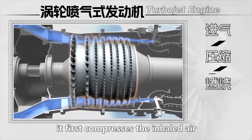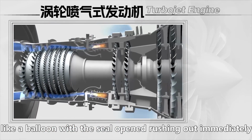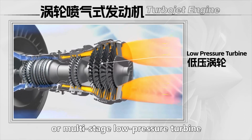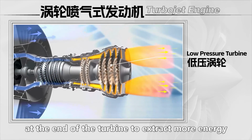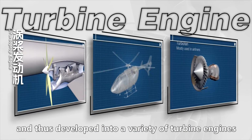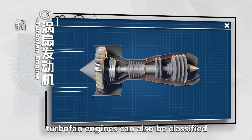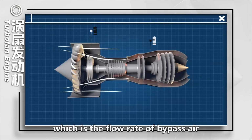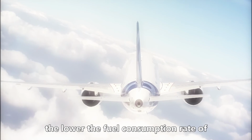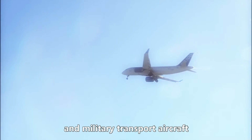It first compresses inhaled air, burns it, and then ejects it to provide power, like a balloon with its opening released and air rushing out immediately. Scientists added one-stage or multi-stage low-pressure turbines at the end of the turbine to extract more energy. This energy is used to drive different kinds of power sources, and thus developed into a variety of turbo engines. As an advanced version of the turbojet engine, turbofan engines can also be classified according to bypass ratio, which is the flow rate of bypass air to air passing through the core. A larger bypass ratio lowers the fuel consumption rate of the engine and means less noise. They're widely used in large civilian and military transport aircraft.